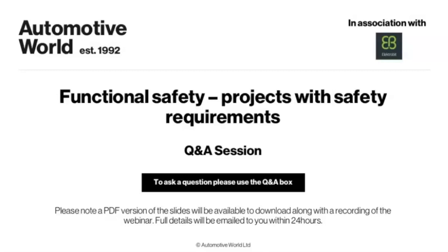The OS, TIME, E2E, and RTE are developed according to the assumption of ASIL-D. That should cover the whole range of integrity levels, so it needs to be developed according to your safety process. The normal QM measures are not sufficient.